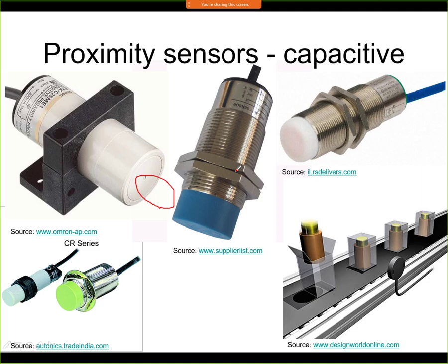Capacitive sensors detect the conductive materials as well, so you will see it as well. But if you approach a non-conductive material such as a piece of plastic or wood, then it will be detected only by the capacitive sensor. And if it's an inductive sensor, you will not see any reaction at all.